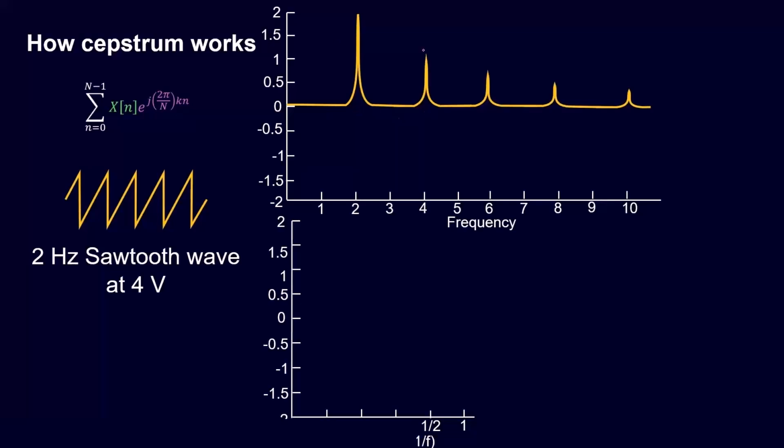So here I have a sawtooth wave, and if you had to describe a sawtooth wave in the frequency domain, Olaf, what would you say that it looked like? Now I have the basic frequency and all the harmonics with a certain level. Right. So I have my basic frequency at 2 hertz, and then a sawtooth wave is made up of a combination of equally spaced harmonics that happen to be the 2 hertz spacing apart, the fundamental frequency apart. So here's what I'm going to do.